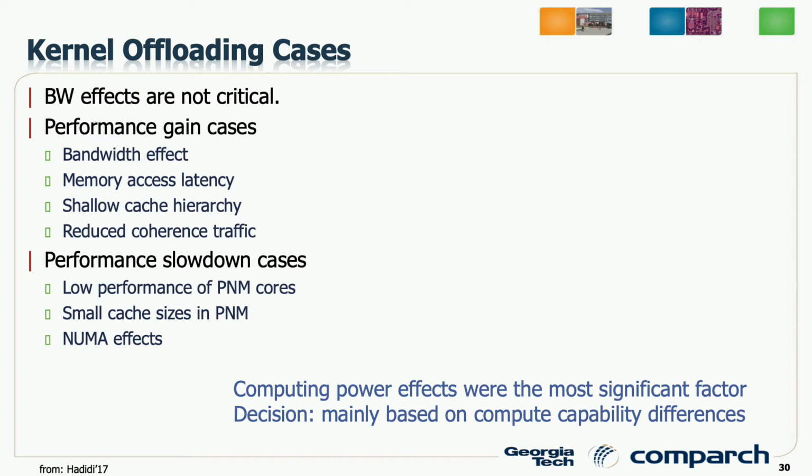But in this case, when you offload these kernels, these performance differences give a good indication of whether one needs to offload to the PIM or not. But one of the reasons that we want to use PIM was energy savings. The main idea is that if you do not send the data from memory to the core, and just perform the computations in the memory, then we could save the energy of the data transfer.